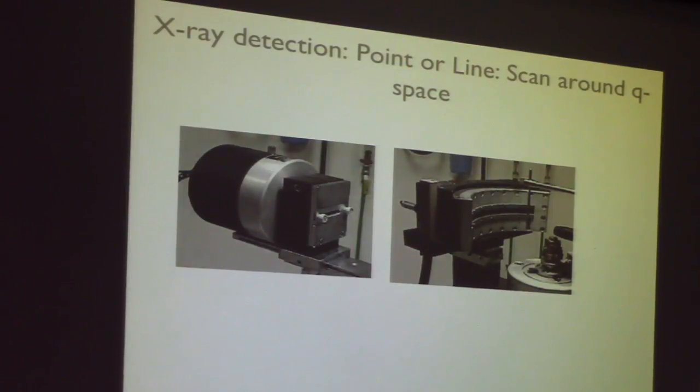You can say, I only want to accept pulses above this lower threshold and below this upper threshold, and these are the pulses that I know have the energy of my incident X-rays. Pulses from some different energy process it will ignore, and it will only accept the ones with your incident energy. So these are very nice detectors, actually.